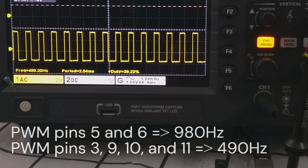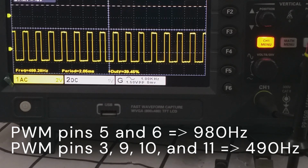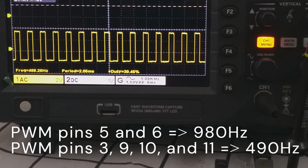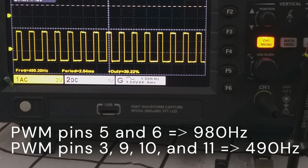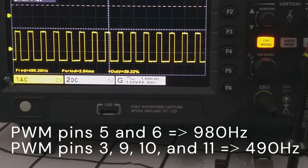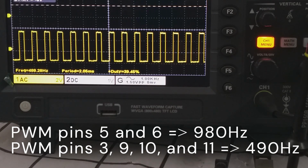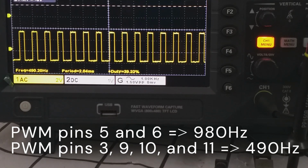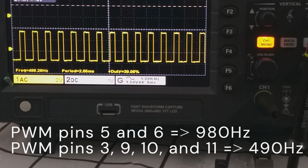From here we can see that two channels are providing higher frequency compared to the rest, which is 976.5 Hertz, at channels number 5 and 6. And the rest of the channels, which are 3, 10, 9 and 11, are producing 490 Hertz with the same duty cycle for all the channels.